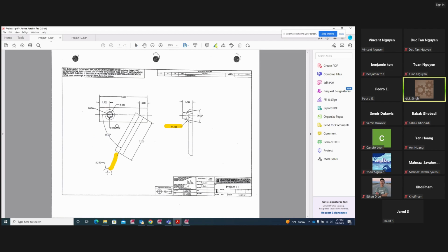So let's go ahead. We can have this as an origin, and at the origin we're going to create a 1/2 inch circle, which is going to be a through hole, and then radius 400, which is diameter 800. There's another circle, and that circle is going to be draft. So those two arcs are going to be at Z 1.7 in the construction plane top.